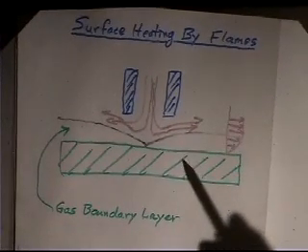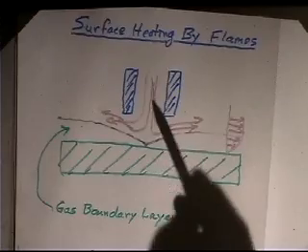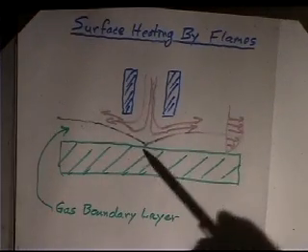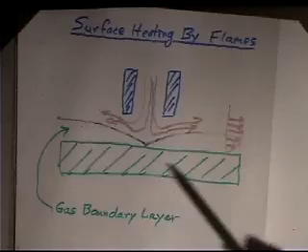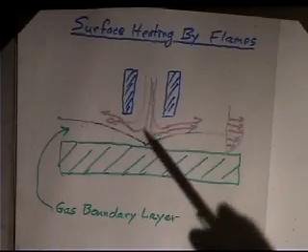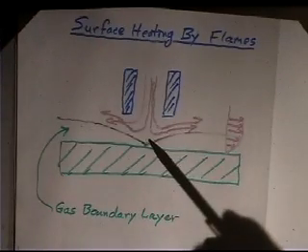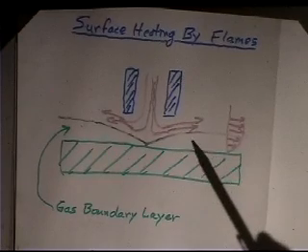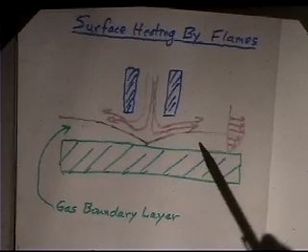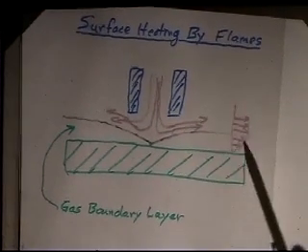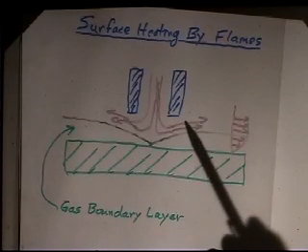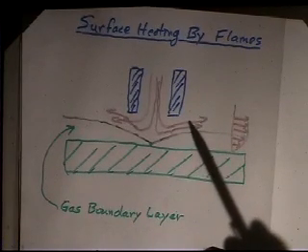3,000 degrees centigrade flames? Well, it turns out if I have this flame that's shooting out, I get a gas boundary layer against the surface. So I've got a surface of some solid or some liquid here. The gas shoots out, and you end up forming a lower velocity. You have friction against the surface of the condensed phase, and the gas has a lower velocity in the boundary layer than up here. How many people have not studied boundary layers in some other engineering course?